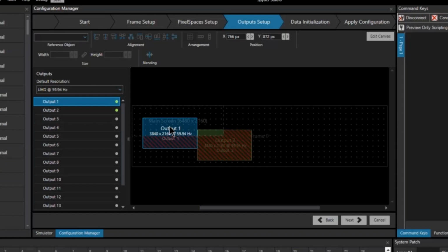This is what you would do if you were going to be manually positioning outputs for, say, an LED wall that had different areas of interest, or areas of responsibility. So in this case, you can still manually do that, and I'll show you a couple ways you can populate this blended screen here. So I'll start with output 1. Go ahead and put it at pixel 0 horizontally and 0 vertically, X and Y. And now that's mapped to the upper left side of that spot.